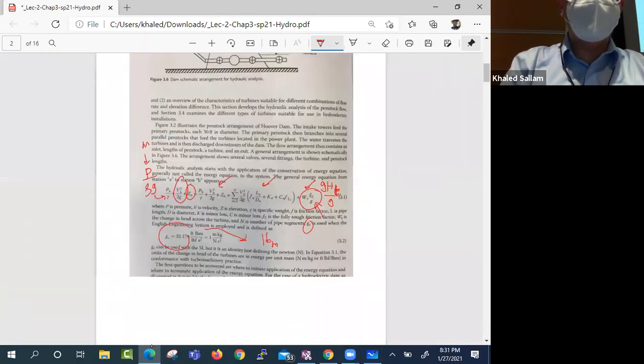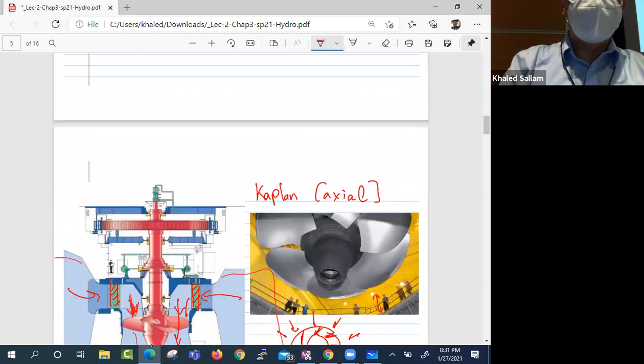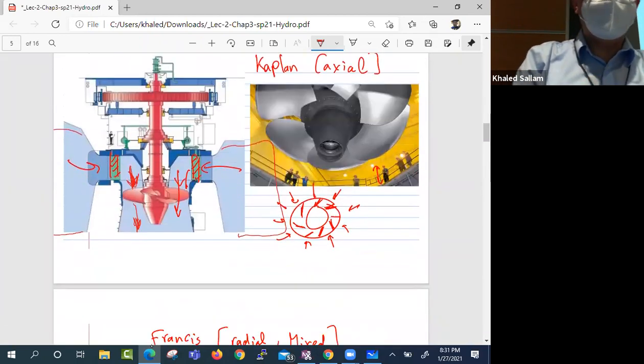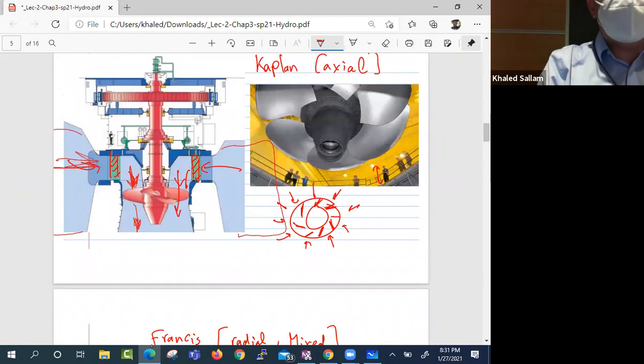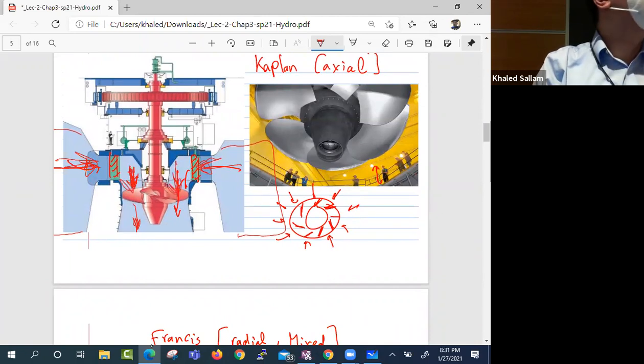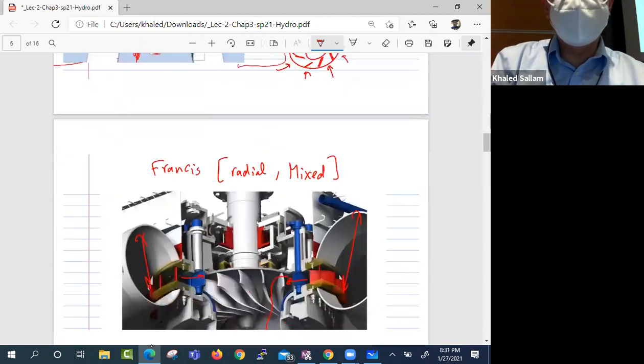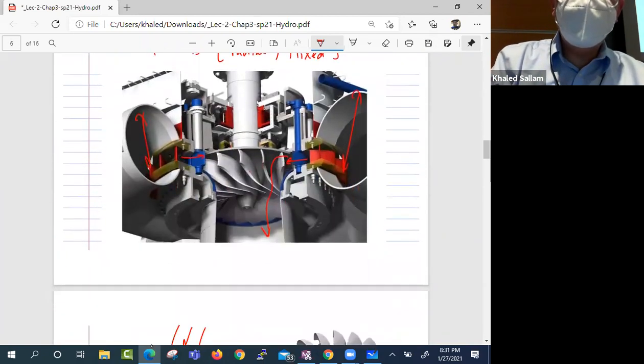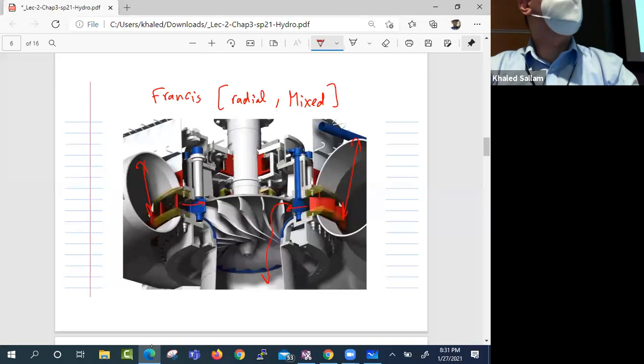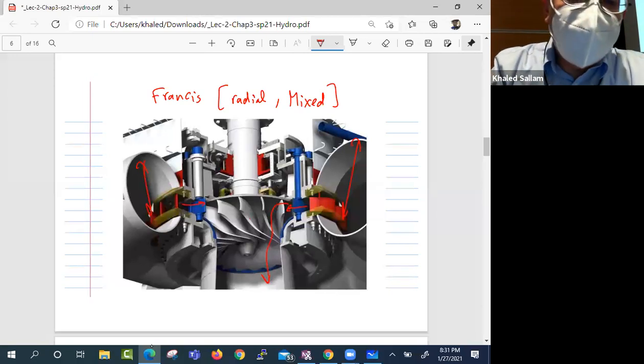How does the flow approach the rotor? So I'm basically trying to tell you to forget about this inlet and this inlet. Just look here and here. He comes axial and leaves axial. That's called an axial machine. The radial would be this. This is called a Francis turbine. So those are the rotor plates.